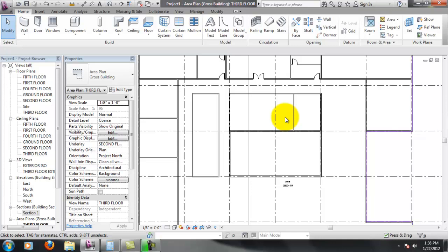And then I need 1 water cooler or 1 water fountain per 100 people on this floor. So that means I'm going to need 2 water fountains on this floor to meet code. And I need at least 1 service sink on each floor, or a janitor's closet or something similar to that. So those are some things I want to make sure that we include in this Revit file.